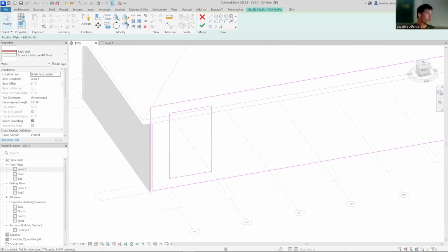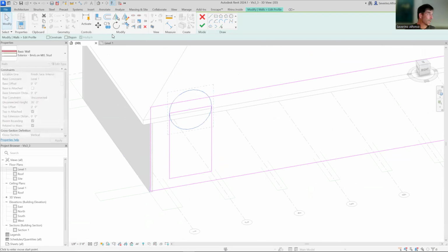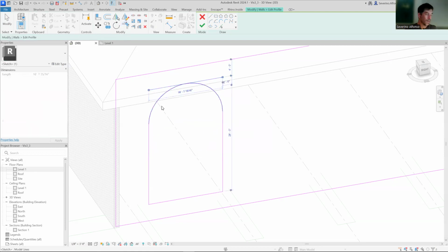I can do a circle, which is this option, go to the middle point, click at the end, select it after escaping, and B, it's the move command, go to the top point, come down. And now I need to do some trimming here. In order to do some good trimming, you need to do some splitting as well. SL, split element, or split element with gap. It doesn't really matter. I'm going to split element in the middle circle and use again TR in the trim option. Say this side with this side, this side, this side, and delete this one.